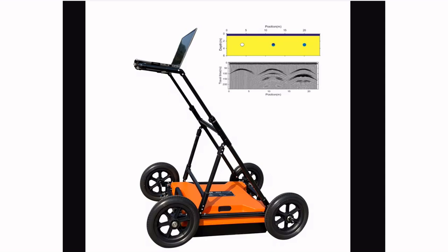and with the advent of digital signal processing techniques and also 3D processing capabilities, this GPR has become widely used in almost all the construction companies. So, as we are discussing concrete inspection, we will see a few instances in which this GPR can be used. The application of concrete inspection mostly includes locating the spacing and depth of the reinforced steel and